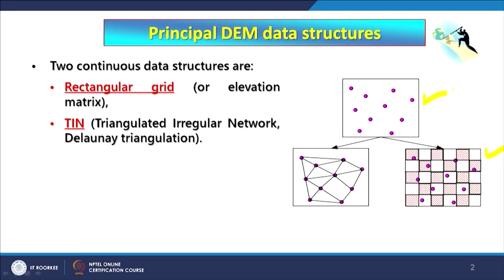The important point to see is what happens on the margins when TIN is developed. Because when using point data and creating a raster through interpolation techniques, we can decide what the extent of our raster should be, and also what the resolution or the cell size equivalent to ground is going to be.